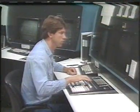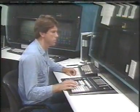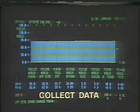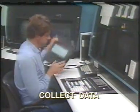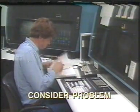When we say an operator should use logical thinking, we mean he should go through the following steps when working with a distillation column. The first thing he does is collect all relevant data on tower operating variables. Then he analyzes this data to determine if there is an operating problem.